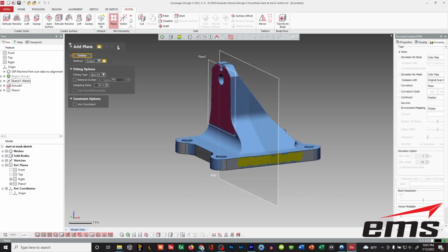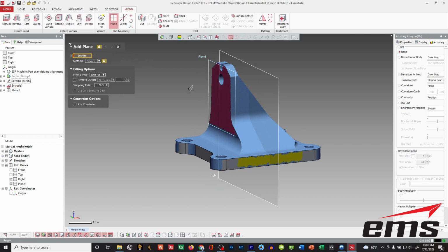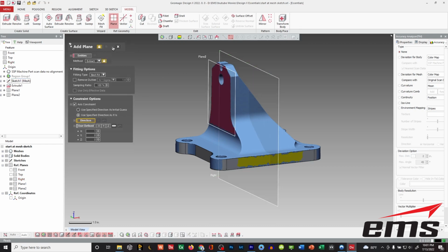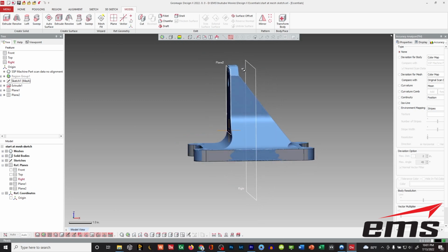So what I want to do is, when I do that extract, I'm going to pick again, and this was turned on, but we had a different plane pick. Then I'm going to say constrain the axis, and for direction, I'm going to pick this right plane there. And now when it creates the plane, I close it, and it looks almost the same.